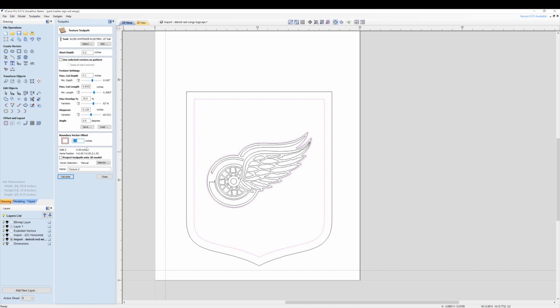And actually, I'm going to go just a little bit more than 1/8 of an inch, just to make sure that there are no errors as far as the piece shifting just a slight amount, or if there are any small minor discrepancies in the actual bit size. So instead of 0.125, I'm going to change that to 0.13. So it's a little bit more than the radius. We're going to offset it towards the inside.